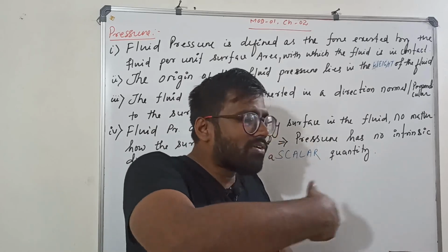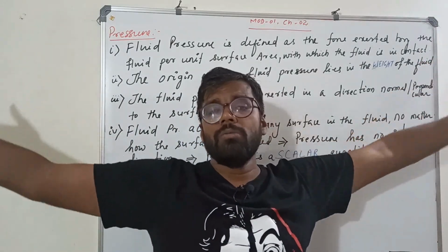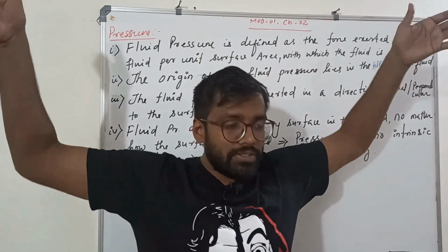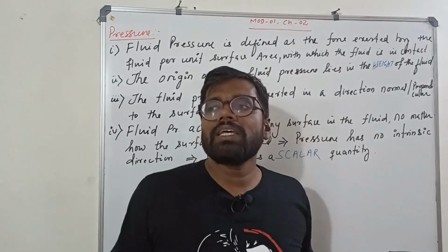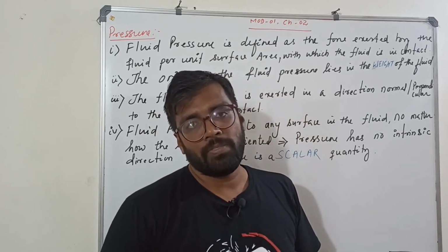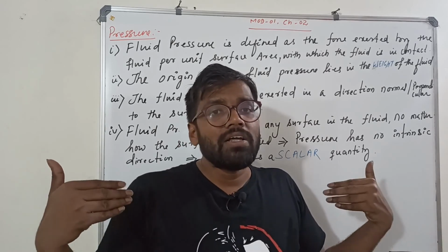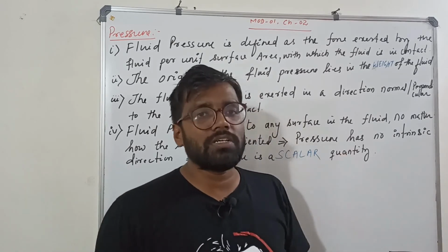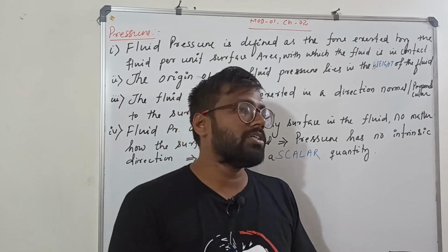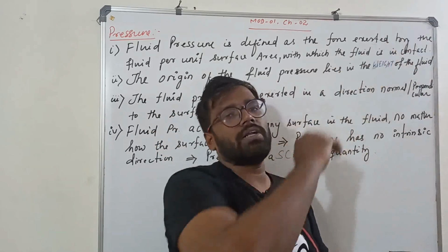With wheels, the area of contact is very less, and the tank is a very heavy body. So it will sink inside, or it won't get the required speed it needs. When you use a belt, you are increasing the area. When you increase the surface area, what happens to the pressure? The pressure automatically decreases, hence it can have a smooth run.